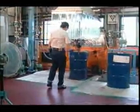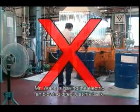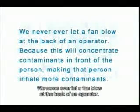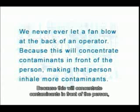Mr. Wang is having the electric fan blowing directly at his back. Is it correct? Of course not. We never ever let a fan blow at the back of an operator, because this will concentrate contaminants in front of the person, making that person inhale more contaminants.